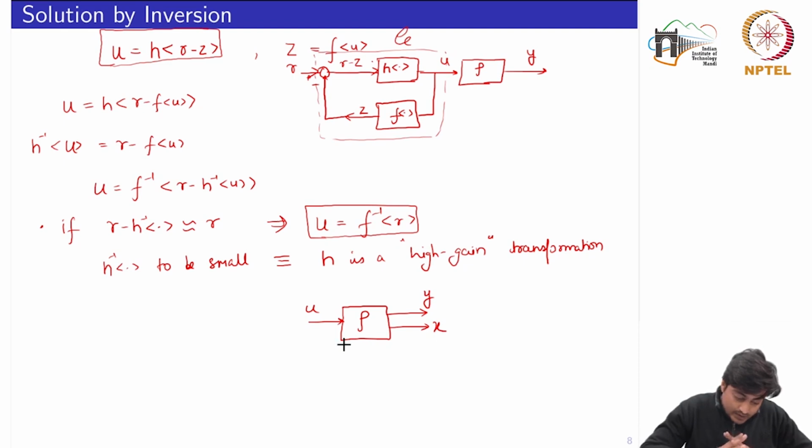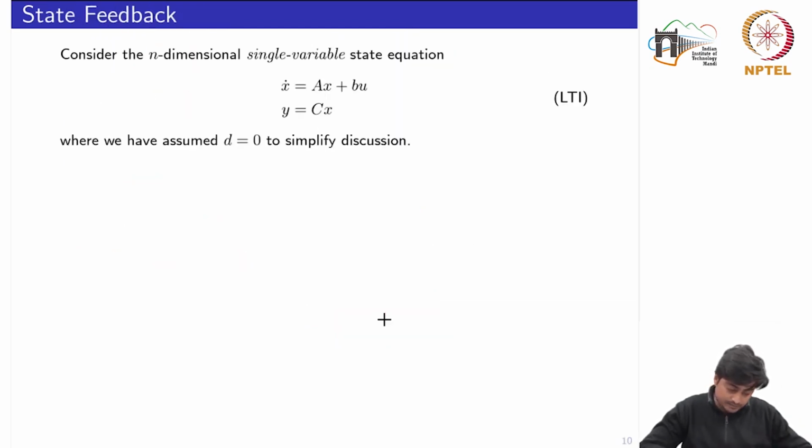So in fact, whatever control schemes you would see, we need to use the inversion. Now this inversion we are going to implement by using the feedback mechanism, and explicitly we would use the feedback from the states. So we are going to discuss various tools for how we can design that state feedback mechanism.